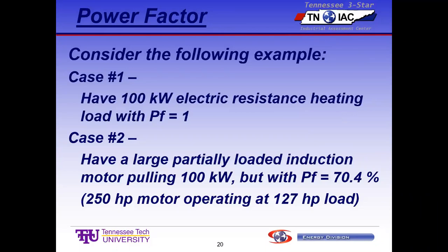The power factor on that, we're going to say, is 70.4%. So if you put a power meter on it, or the utility meter is going to see 100 kW for both of these loads. But you're going to see a big difference in current to supply that load because of the low power factor. And that 100 kW is equivalent to about 127 horsepower load on that motor.